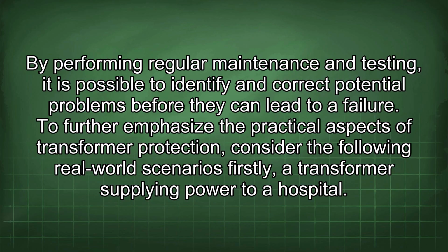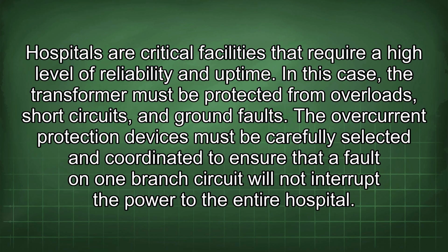To further emphasize the practical aspects of transformer protection, consider the following real-world scenarios. Firstly, a transformer supplying power to a hospital. Hospitals are critical facilities that require a high level of reliability and uptime. In this case, the transformer must be protected from overloads, short circuits, and ground faults. The overcurrent protection devices must be carefully selected and coordinated to ensure that a fault on one branch circuit will not interrupt the power to the entire hospital.